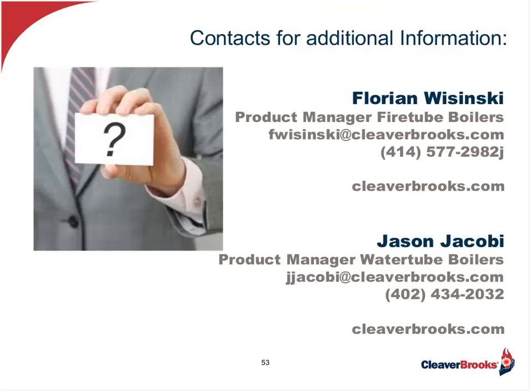Yeah, we do. There are what we call commercial water tube boilers that are available out there today. Cleaver-Brooks has some, and some of our competitors have them as well, that will operate at those higher pressures and lower horsepowers. Normally they are either a coil type or a water tube boiler, a boiler as opposed to a generator. That's how you would get to that pressure in those lower size ranges.